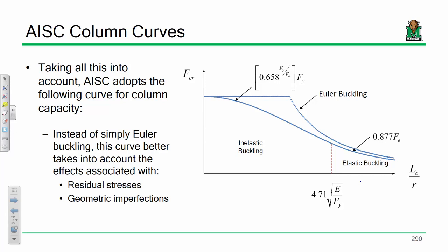The more slender a column gets, the weaker it is. Okay? So just so you're aware, see this little thing right here? That's that cutoff curve I showed you before. But in reality, the capacity is reduced a bit because of imperfections and residual stresses. So first off, this dashed curve is the theoretical one, but really we're after this solid lower curve. Okay. And the second thing is, as the curve gets longer, the capacity gets lower.